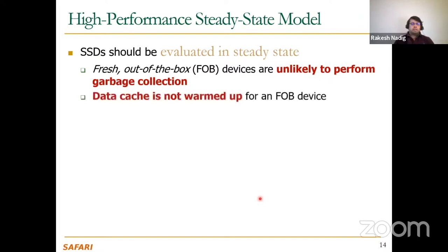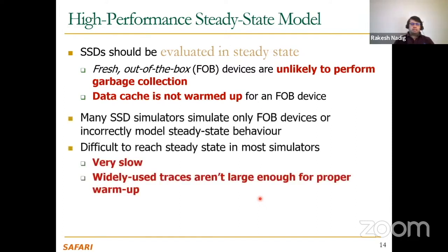Also, in a new SSD device, the data cache is not warmed up, which means that there won't be any entries in the data cache, and the request will have to go to the backend all the time, and it won't be served from the data cache. So many SSD simulators actually simulate only fresh out of the box devices, or they incorrectly model the steady state behavior. And why is this difficult? It's very slow.